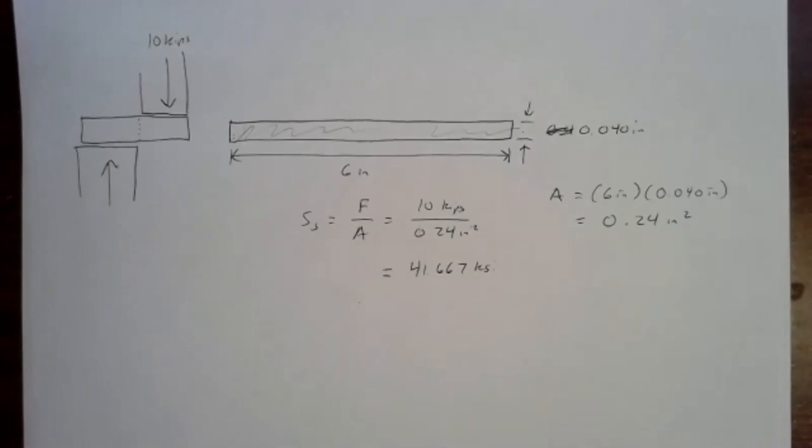Now, it's possible you've had this experience in cutting sheet metal. Maybe you try to cut it, but you just didn't push hard enough. What that means is that you didn't create enough shear stress in the material to break through it and cause it to exceed its maximum shear stress. Now, of course, the way we really do it's a little bit different than this, but that's the basic idea of shearing through anything or punching through something.